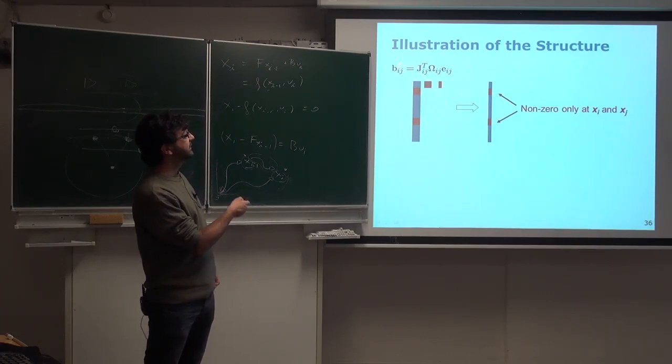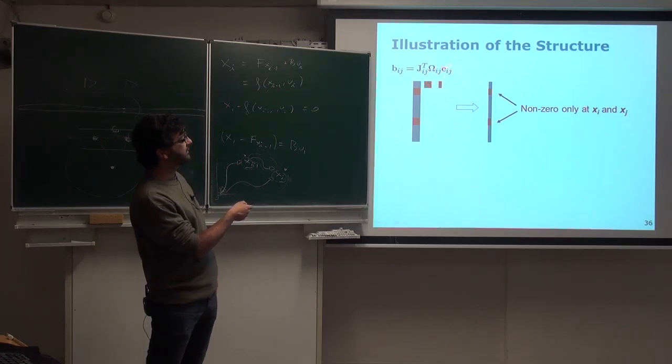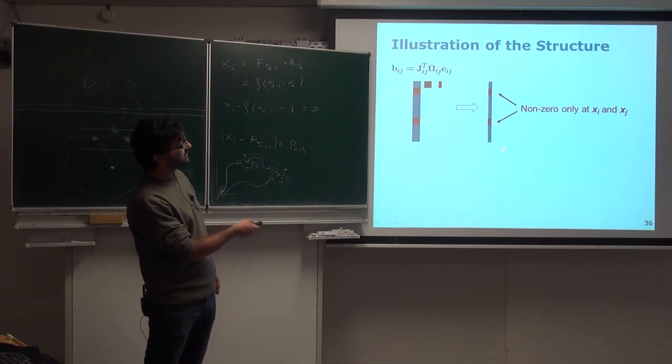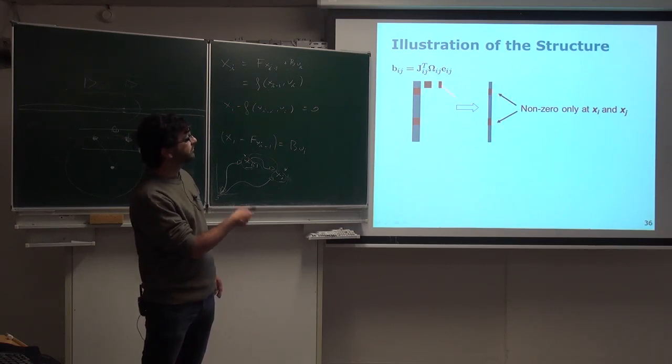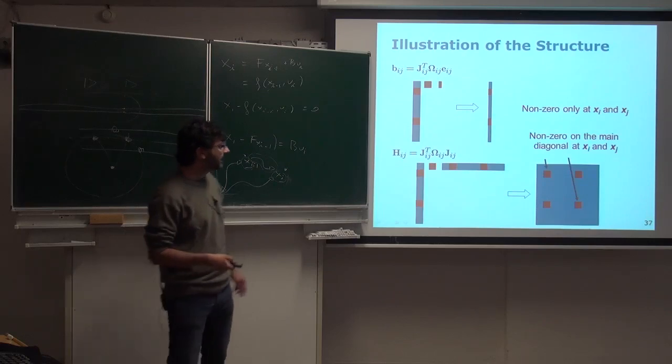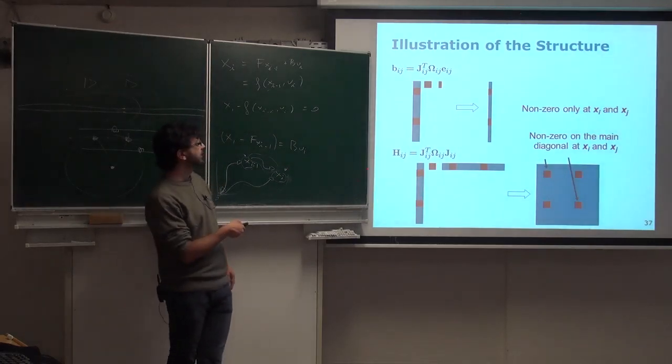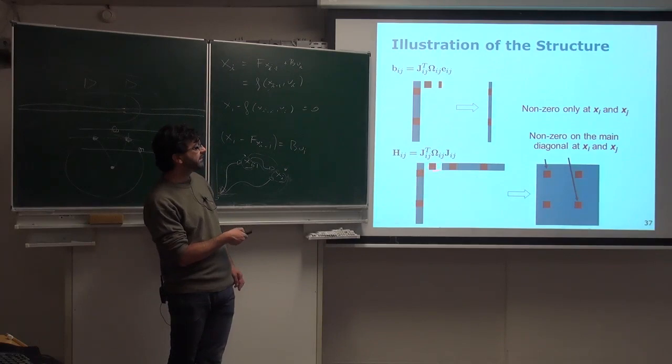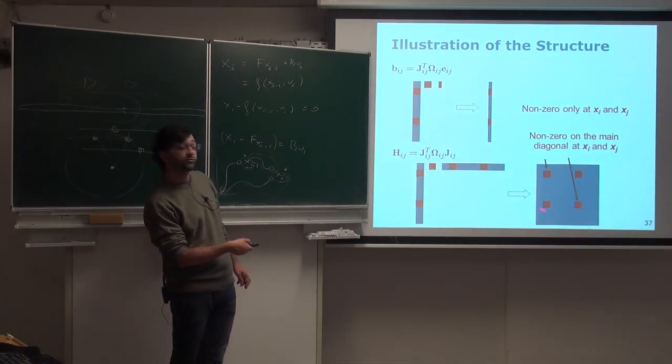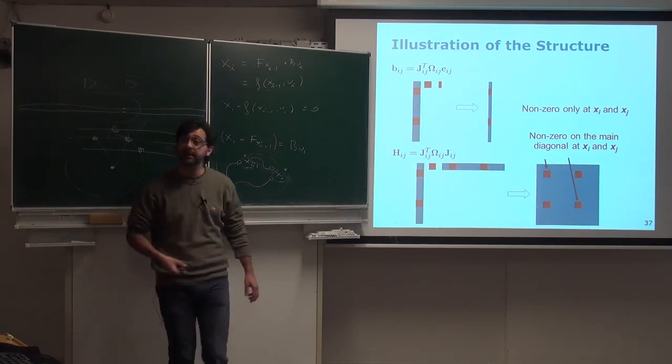We have that the b's are, when we multiply this by the information matrix of the edge and the error, we get that again we have a sparse b for ij, and the same thing applies for the H. We get our Jacobian here, which is sparse, we get the information matrix, we get the other Jacobian here. We end up in a matrix which is very sparse, and it's non-zero only in the 4 blocks that belong to the ii block, jj block, and the mixed ij blocks.